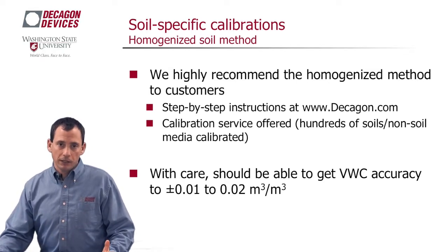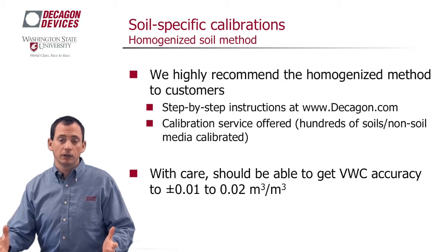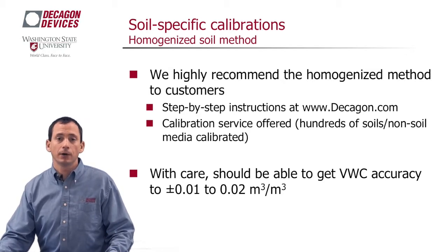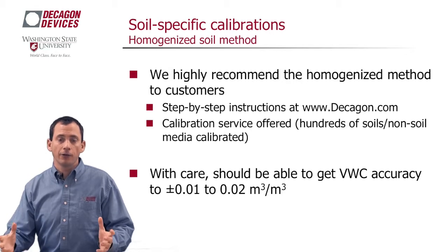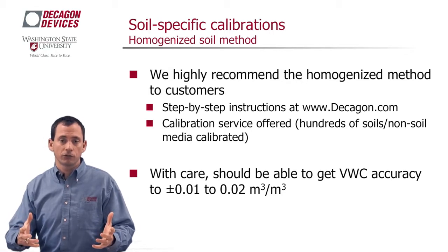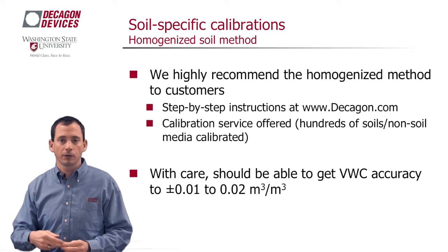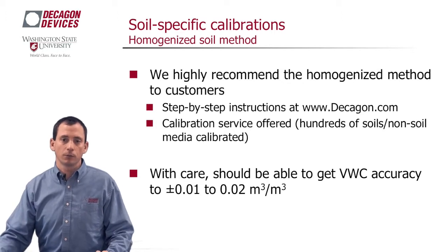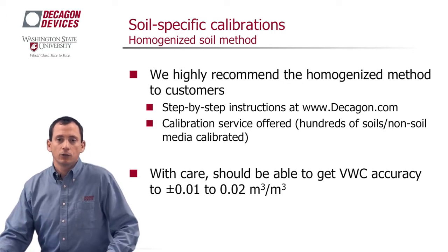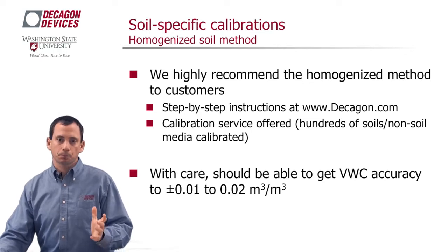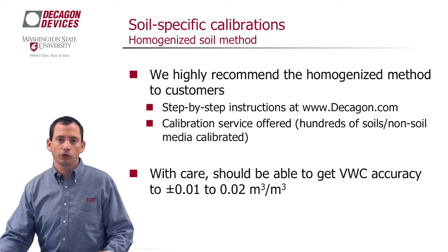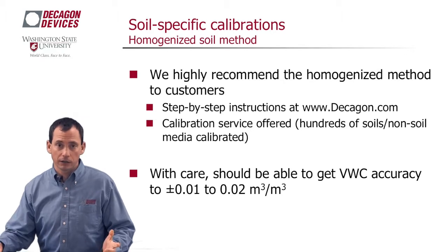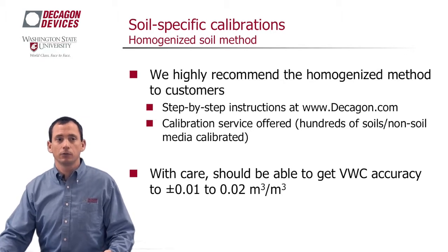My preference would be that you do this instead of us do it. I mean, we're happy to do it, but I think there are other benefits that you would get from doing this yourself. It really helps you be familiar with some of the pitfalls on the probe and probe insertion and gets you some good hands-on experience with the probes before you take them to the field. So either way, if you need really accurate measurements or if you're working in a non-typical soil, then the soil-specific calibration is a good idea. It's always a good idea, but sometimes you don't need it, but sometimes you do.